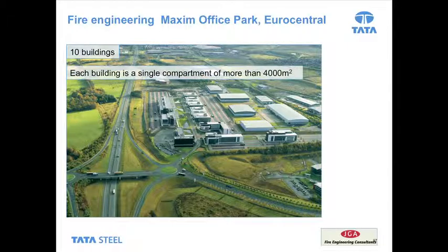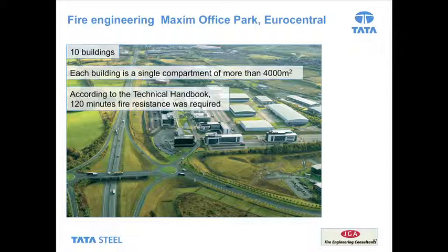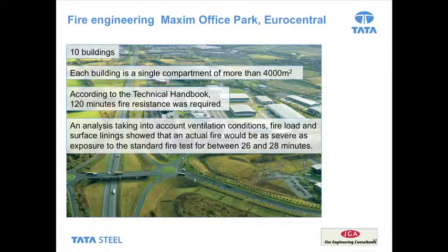They obviously didn't use the English building regulations. They used the Scottish, if you like, variant. But again, if you looked at the technical standards in Scotland, what they told you is that many of the buildings on that site would have needed to be fire protected to 2 hours or 120 minutes. The engineer, which was Jeremy Gardner and Associates, did some analysis, and they used that time equivalence method. And when they compared that to the standard fire test, the actual fire period that they needed was just short of 30 minutes.